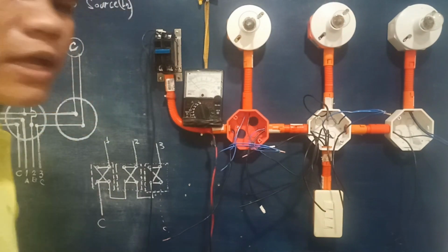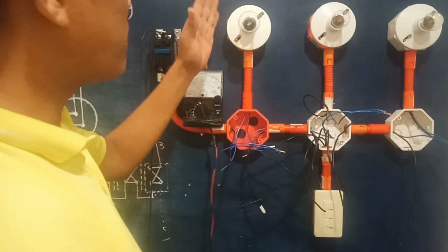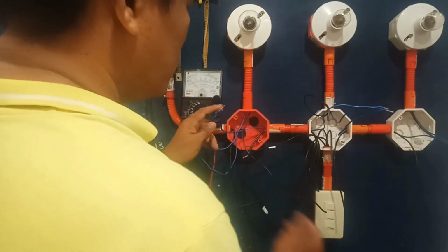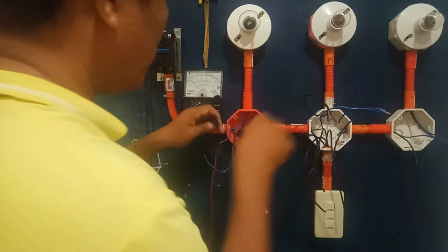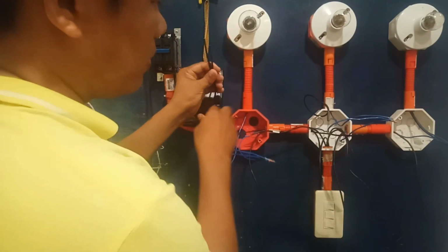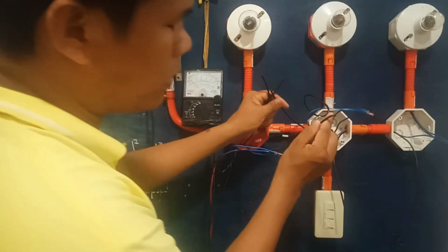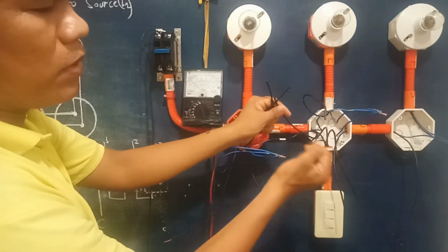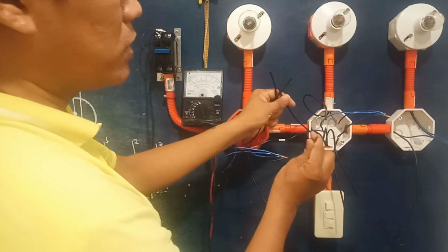So in the second cycle, of course, the connection is from bulb A to the first single pole switch. So we have here now another wire, this one, and on the number 1 indicator a while ago, one groove here, meaning indicated for the first switch of the 3-gang single pole switch.